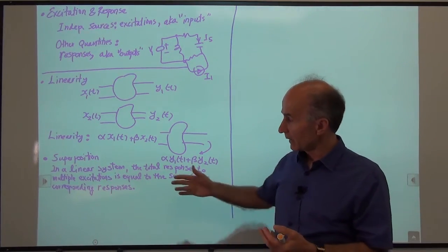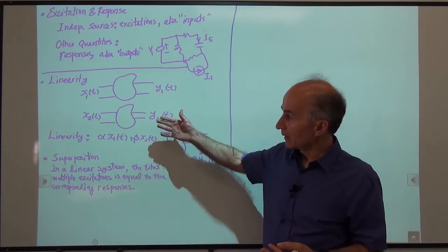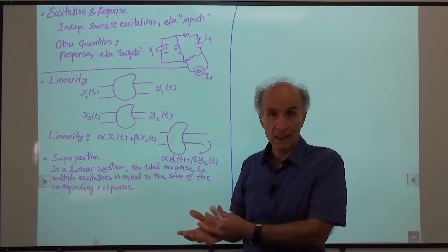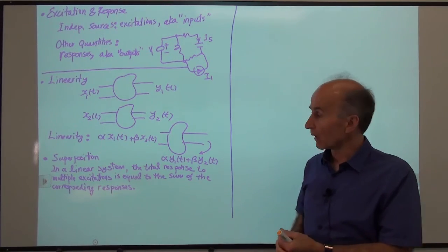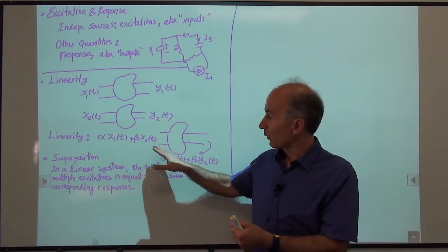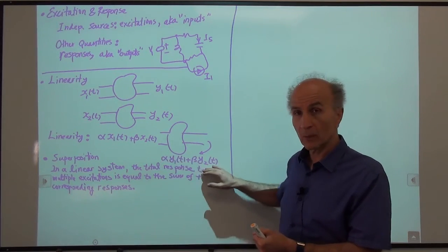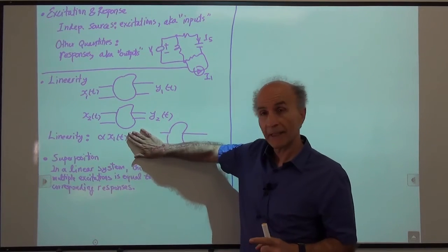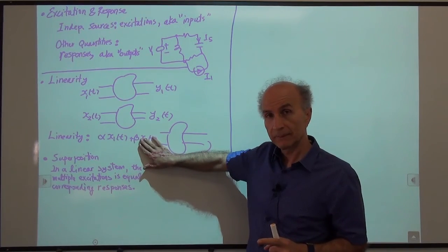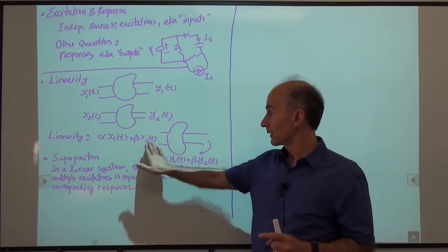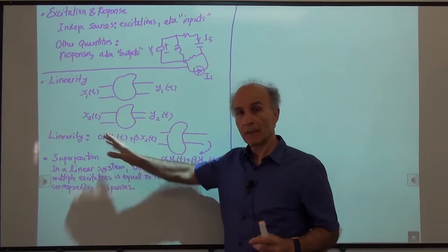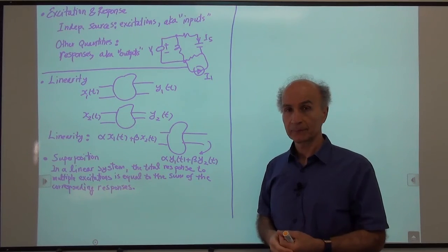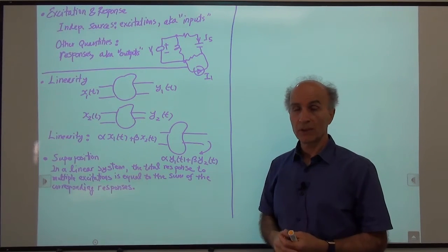So you can see that it's just a natural result of linearity. It's really just a different way of saying linearity for a system, right? All that means is that if I want to find the overall response, what I could do is first I find the response of the system to only this guy, while the other guy is 0. And then I find the response to this guy while the other guy is 0. And then I add up the responses, and that will be the total response that I have. So that's the beauty of superposition.